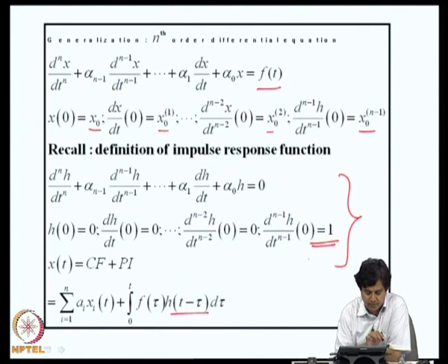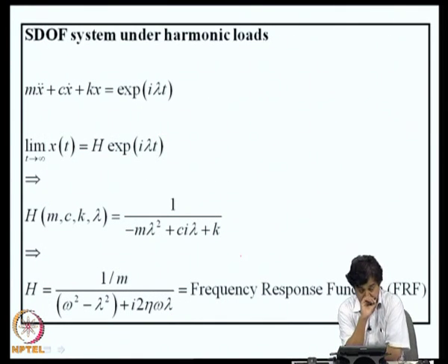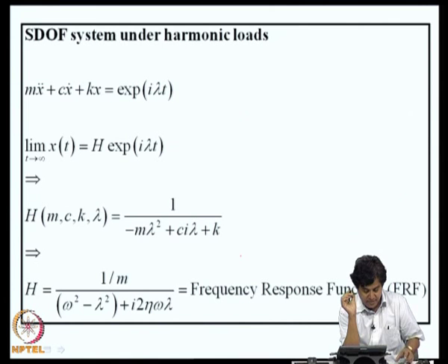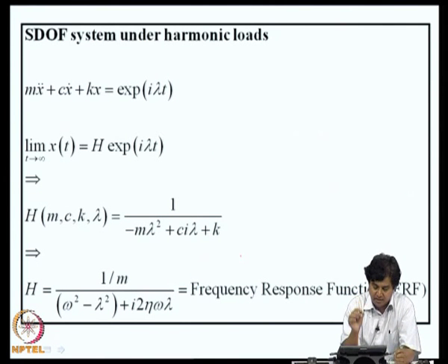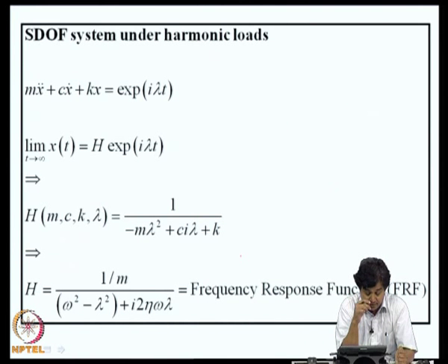So, the theory of impulse response function and Duhamel integral and construction of particular integrals for arbitrary loads is more generally valid. It is not just for second order differential equations. Now, we will revisit the problem of a single degree of freedom system under harmonic loads, and based on this discussion we will try to introduce certain frequency domain descriptions of dynamical systems. This impulse response function can be viewed as a time domain description of a dynamical system.